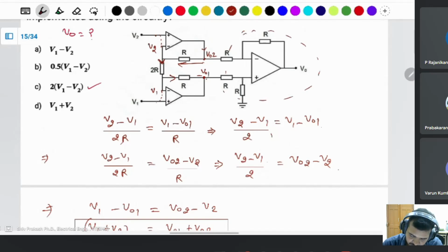Suppose we take some voltage here, VA. Same thing, because of the negative feedback, this is also VA, virtual short.